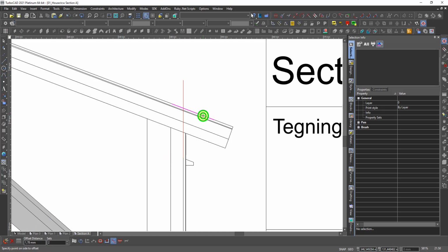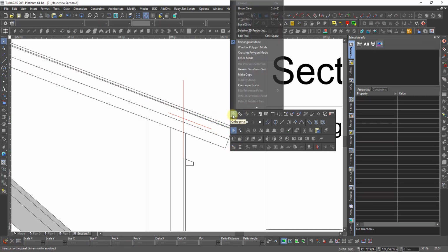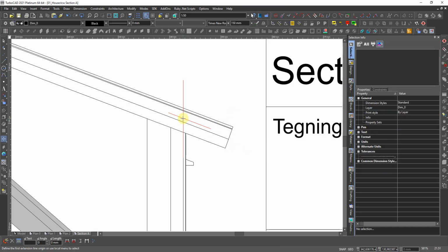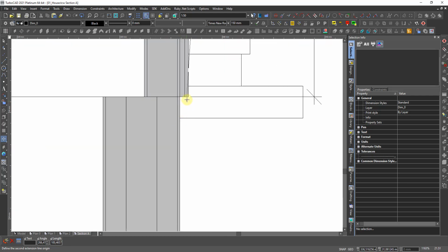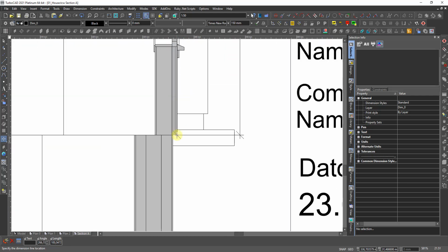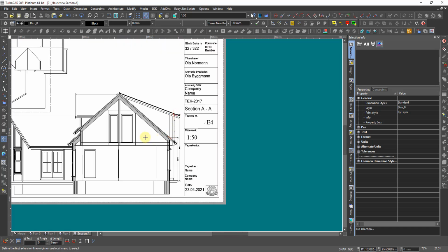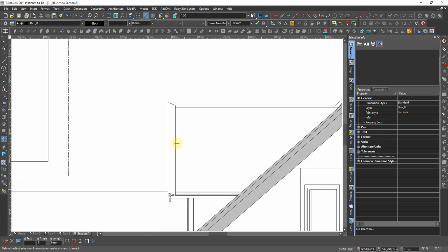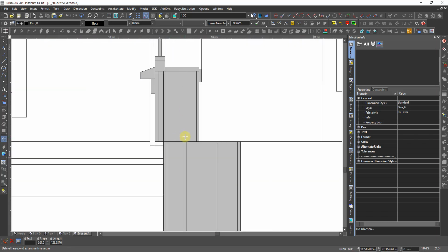I have this line down here. This line I don't need. Then I want to have dimension from intersection here and down to this one, to V. Set that here. I also want one from the ridge up here, from nearest, also again down. I can say to V, and there, take it out.